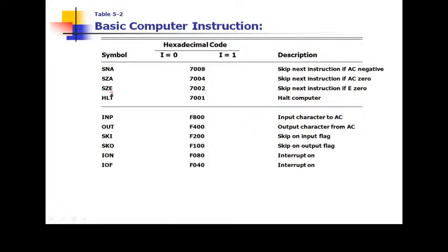Did you understand this? Why are carry and extended accumulator both equal? Obviously, the extended accumulator requires to be filled whenever there is a carry only, right? So obviously the extended accumulator and carry both are equal to 1.